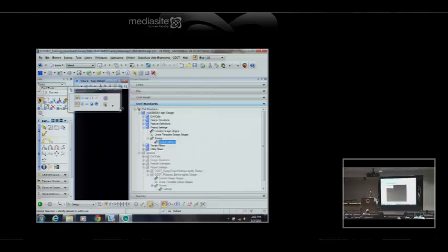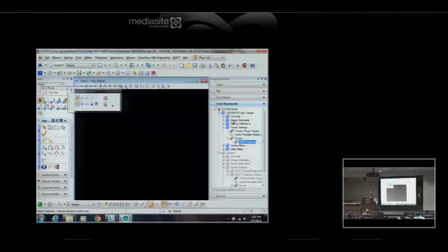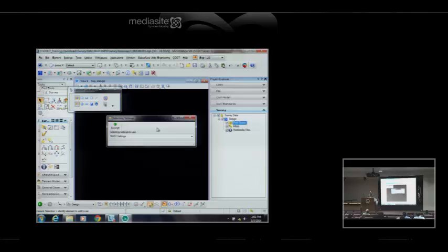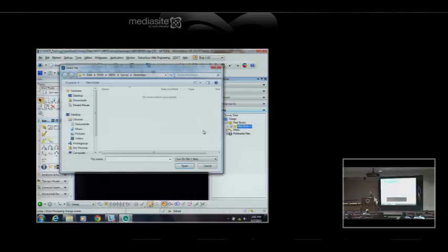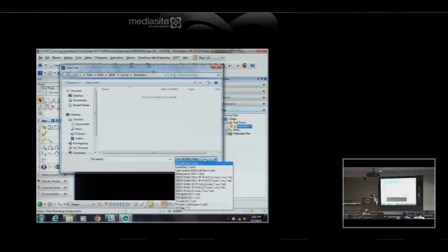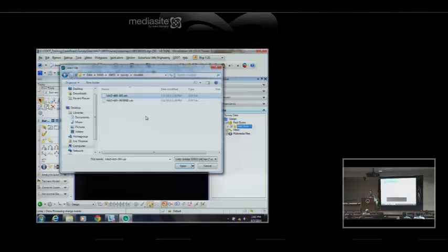Now I'm going to import some data. This is all in the ODOT's training guide. Under survey, my design model, field books, I'll create a new field book. I will use those settings I copied. And in that field book, I'm going to load in a file. And this one is an SDR format. For survey, for raw data, I have two files. I'm going to bring in that one first.